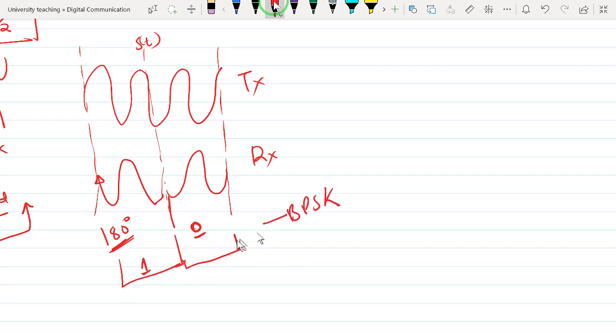That is the essential purpose of carrier synchronization. We are trying to estimate what the carrier signal was at the transmitter and compare that with the one received at the receiver. Once we are able to get the phase of the transmitted carrier, we are able to know how much change in phase has been caused, and therefore what is the likely cause of that change.